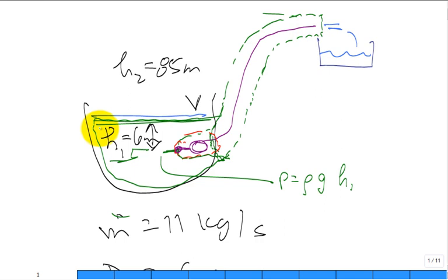It's basically going to be falling into this right here. It's going to be dropping the water level of the lake, true? Do I know the pressure up here an inch below or a half an inch below? Yes, with confidence. It's atmospheric pressure.